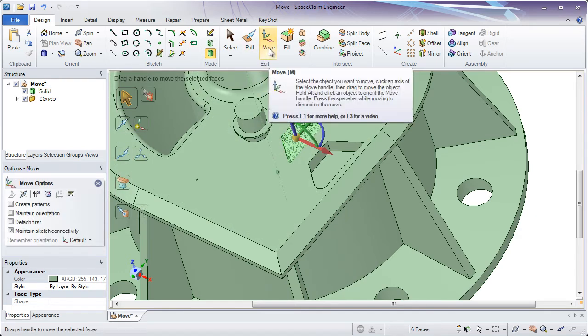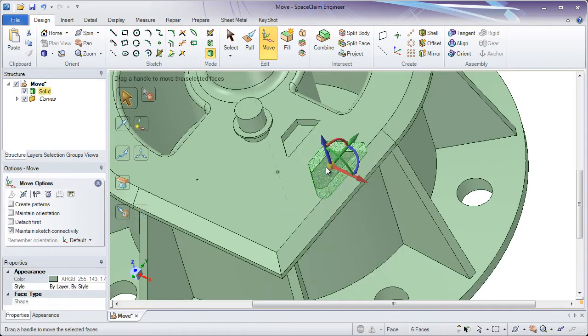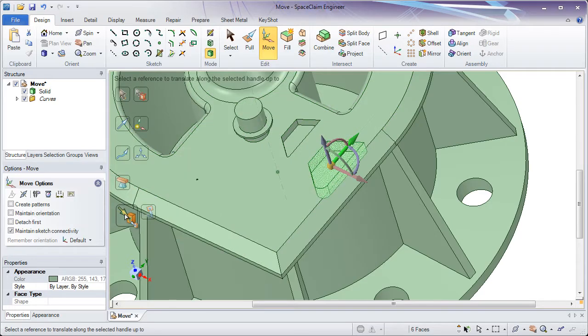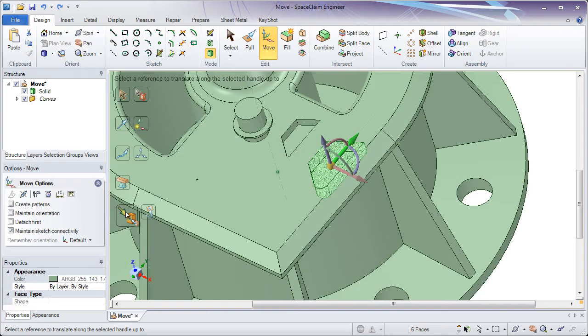For the last thing we'll do, let's look at combining two of the operations we've seen earlier. That's going to be up to and copying with Control. So what I want to do is box select that original depression, and we're going to copy it to a new location. If I click a direction, like this green direction, and hit up to, remember it moves it up to that spot. If I undo and hold Control key before I click this spot, it's going to copy it up to that exact location.